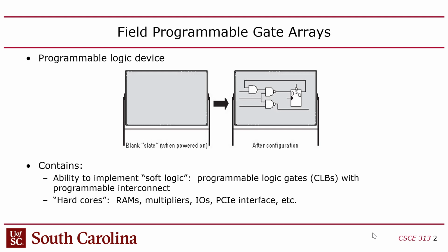So I'm going to very quickly run through a review of basically 611 and 313. If you have any questions, let me know. I'm going to go real fast, though, just to make sure everyone's on the same page. So we're going to be using field programmable gate arrays. They're electronically configured chips, so they're basically a paperweight when you power them up, but then you configure them and they will begin to behave as though you had fabricated a chip, right, with the circuit. The downside is it's 10 times slower than if you had fabricated the chip, and there's 10 times less capacity because of the fact that the reprogrammable gates have to be spaced out more. They're less dense as compared to an application-specific integrated circuit, right?